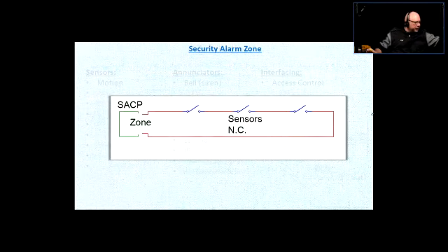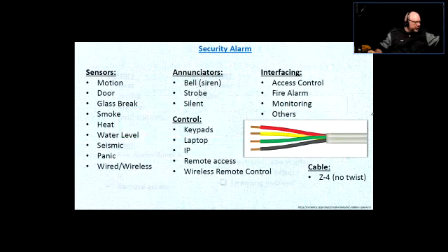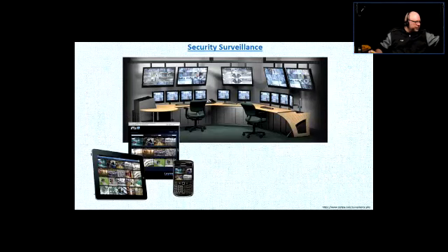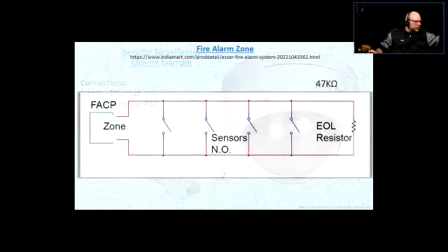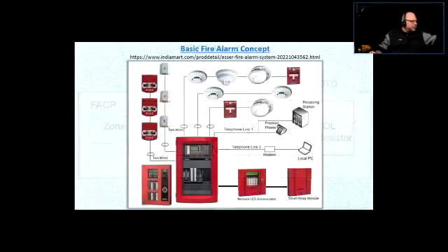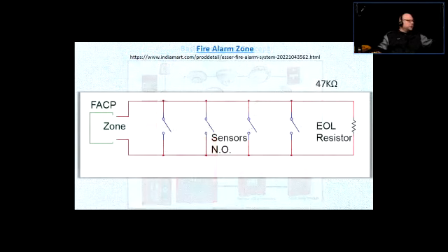Now, as opposed to that, there's the fire alarm zone. Went too far. Okay, here it is. So here's the typical zone for a fire alarm. Notice that all the devices are open for the condition to be considered as at rest.